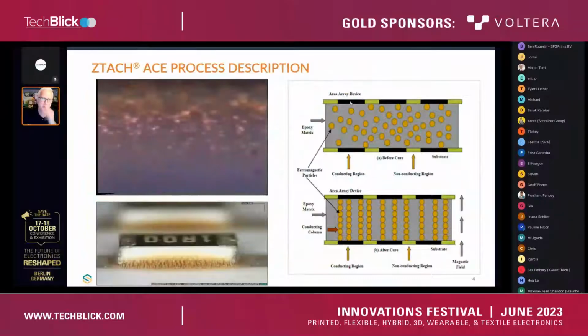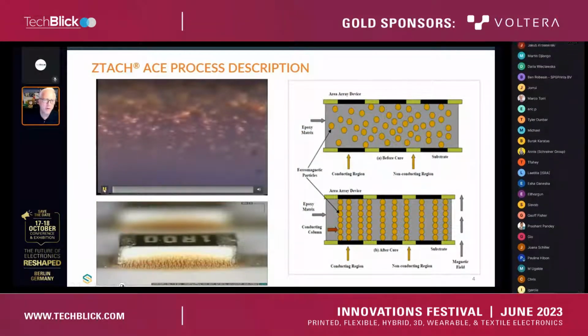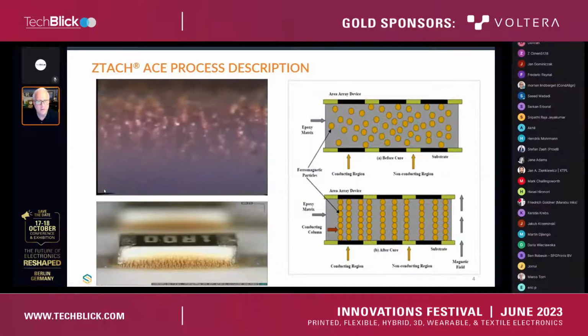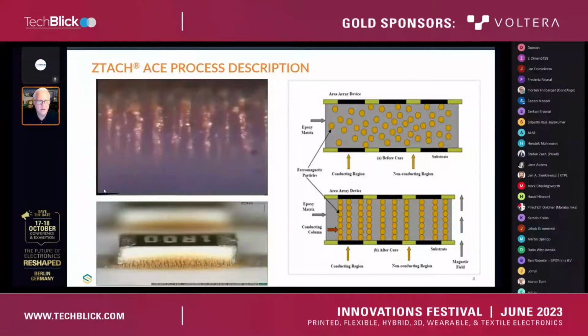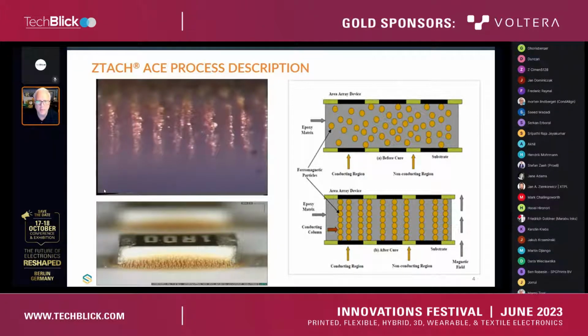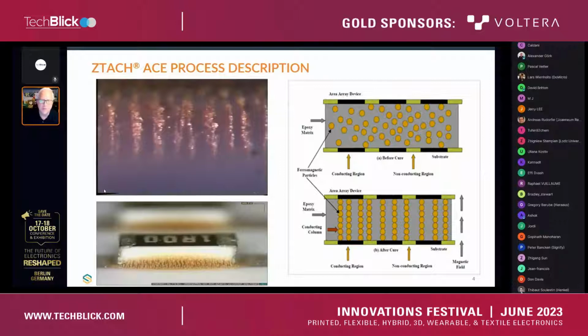And this is how it's done. A video on the left here will show that as soon as we're coming out of the pick and place machine and components are placed down onto the pallet, we get instant particle alignment. They continue this alignment process. And then what you're looking at here is a real-time, non-accelerated X-ray camera looking cross-sectionally through what I like to say is this forest of trees that are being formed. So we're creating all these columns. This technology here is our fine material, which can manage pitch down to 100 microns. We have an ultra-fine material that's proven effective down to 50 and 60 microns, and we're developing a material that can